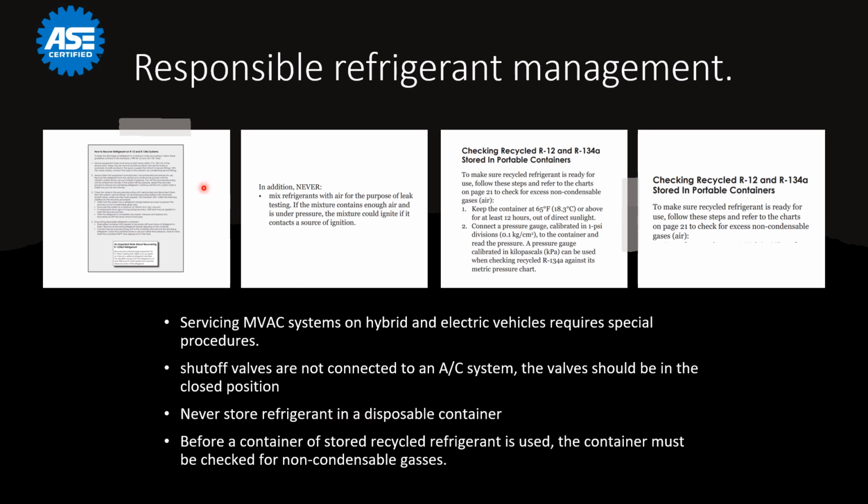Now, one of the things that I found extremely important was in the recovery, recycle, and recharging page on R134A. Most of us who've done AC work typically know what a vacuum is, and how to put the system in a vacuum. When we put the system in a vacuum, I typically did 5 minutes. Most of the technicians that I work with did 5 minutes. But the minimum requirement for this section here is 2 minutes. So the system should hold a vacuum for a minimum of 2 minutes. So doing 5 minutes maybe was a little excessive, but I don't think that really matters. I just noticed that the minimum is only 2 minutes.